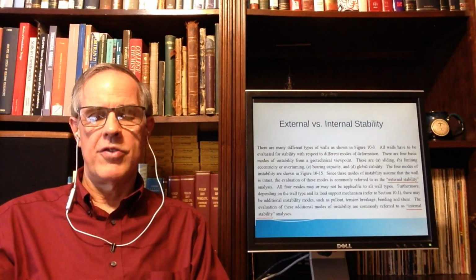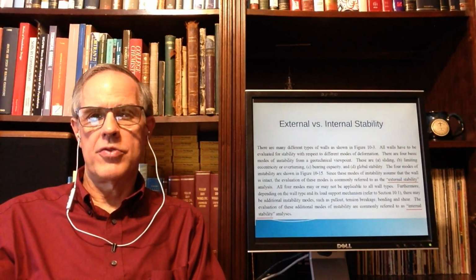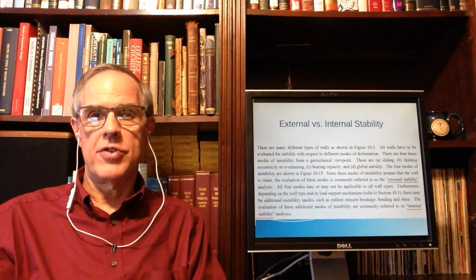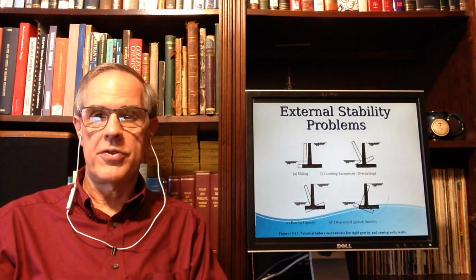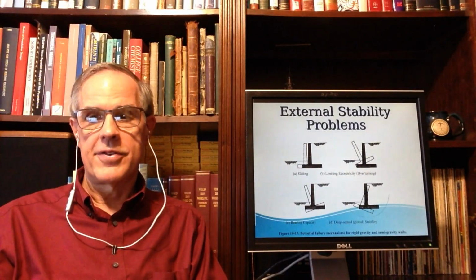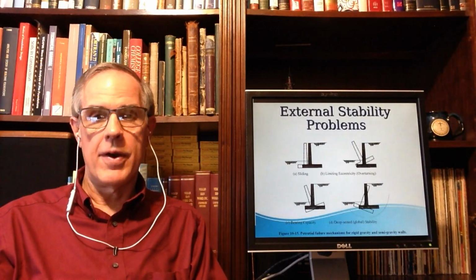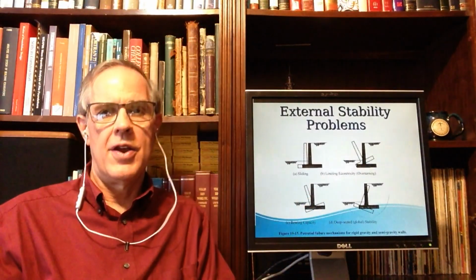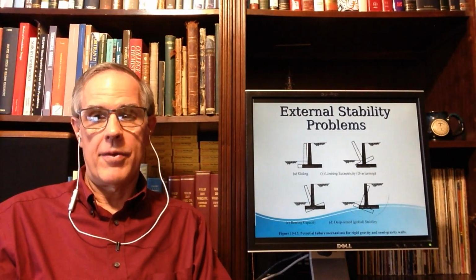The only place where we're going to change that, we're going to do some structural stuff in MSE walls, and we're also going to do bending moments in sheet pile. That's about it. We're going to focus on external stability. Those external stability problems will include, and you'll see this diagram over and over and over again, sliding, limiting overturning, and bearing with gravity walls, particularly bearing capacity failure. I touched on that when we were talking about bearing capacity failures. You can also have a settlement issue as well, by the way.